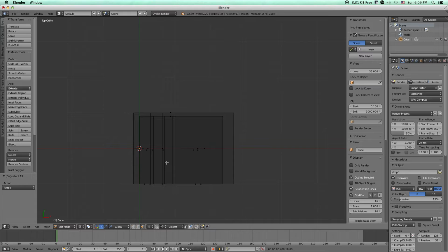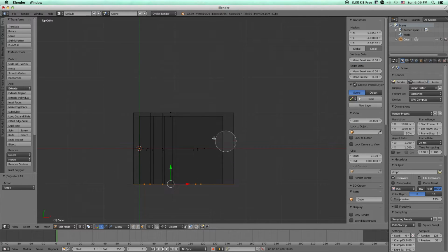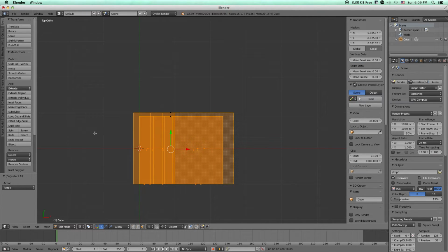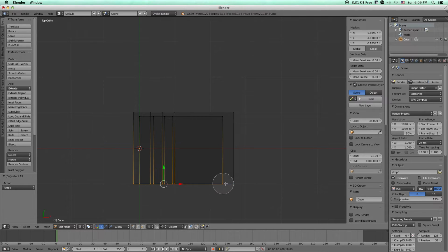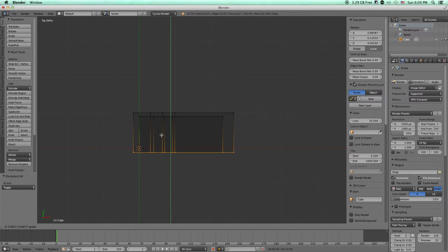And you have 2 different types of selection tools. You can either hit C and scroll up and down on the mouse wheel. And this is just going to be a circle selection tool. And right click to undo it. I'm going to select all again to deselect everything. Choose vertices here. And say I want to select all of these and then move it.